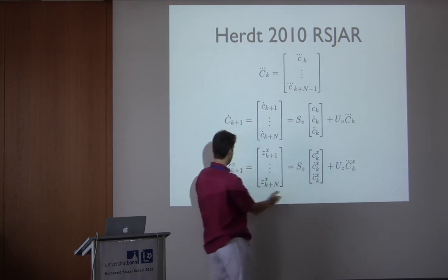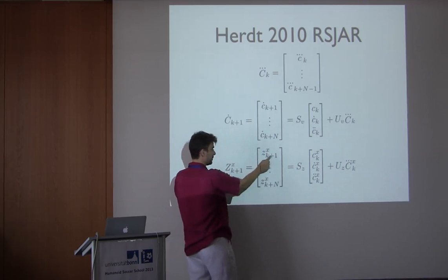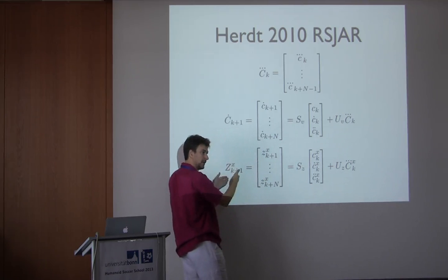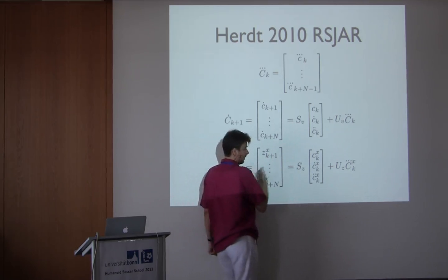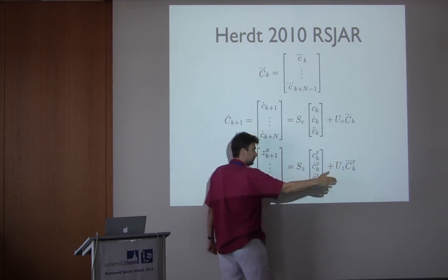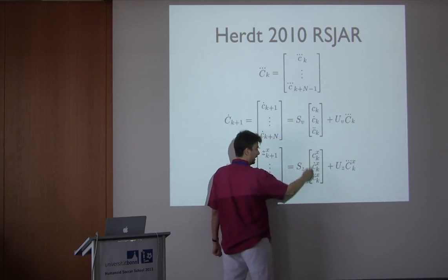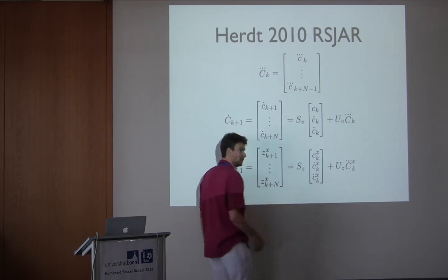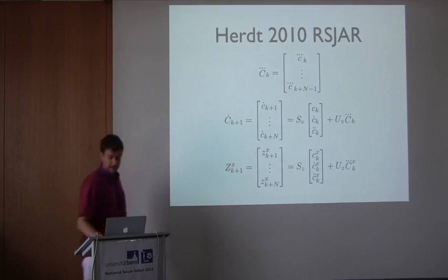So you end up saying the position of the center of pressure for the next n steps, which I put in this vector, is in fact a linear function of this jerk of the n steps, with this matrix, and then, depending on the initial state, so the current state, position and acceleration of the center of mass. So you have these.